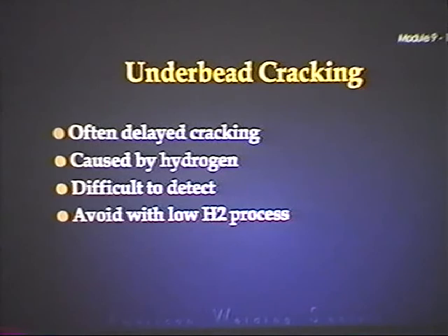Often a lot of guys will check out a rod oven, but they'll get someplace where they get lazy, they don't want to drag an extension cord or something, and they'll have a rod oven, but it won't be plugged in. So when I see that, I make what they call a bouquet, a flower bouquet. I'll open up that rod oven and I'll break every stick of rod that they've got in there, and I'll just leave it bent, laying in his rod oven, and they'll come back and they'll see it and they know that I've been there. I've been called some pretty unpleasant things for doing that sort of thing, but it sends a message. They know that they were wrong for doing that because they violated the code.